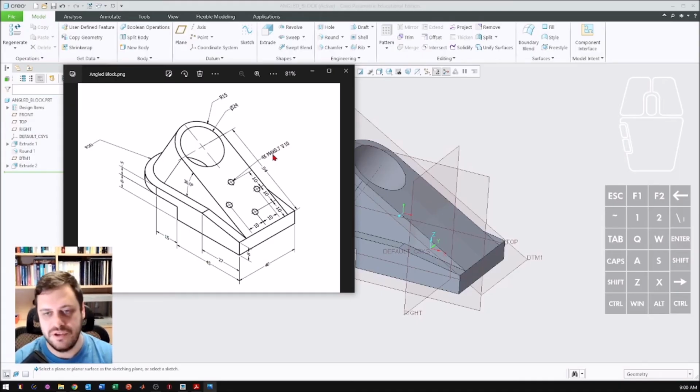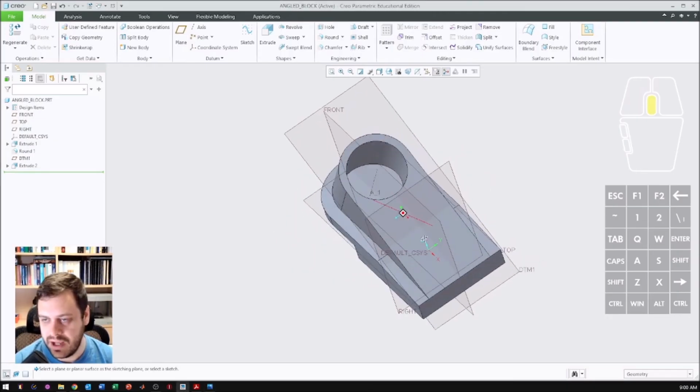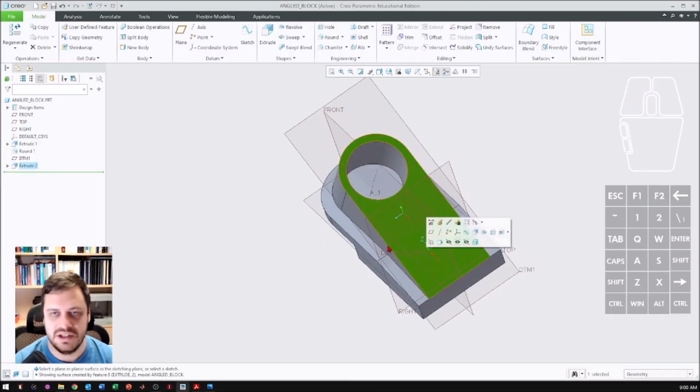at a 4 and assume it's 4 millimeters in diameter. As we get further through the course, I want you to start modeling the DNA in the model, as I like to call it. But for this particular exercise, because we're more concerned about the planes, just use a 4 millimeter hole. And I'm going to use this as an extrude so I can show you what building blocks and setting up your sketch can do to help you become more efficient as well.